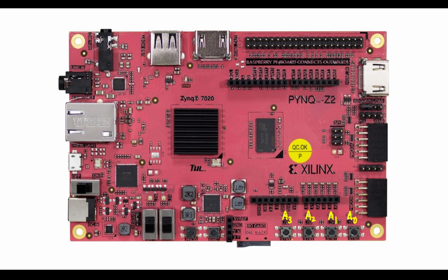So for example, I am pressing just this button, right? So this combination will correspond to 0, 1, 0, 0. Only this button is pressed, nothing else. So this means this is binary 8 or BCD 8. It should show me number 8 on the 7-segment display. So how do I now connect the 7-segment display here?